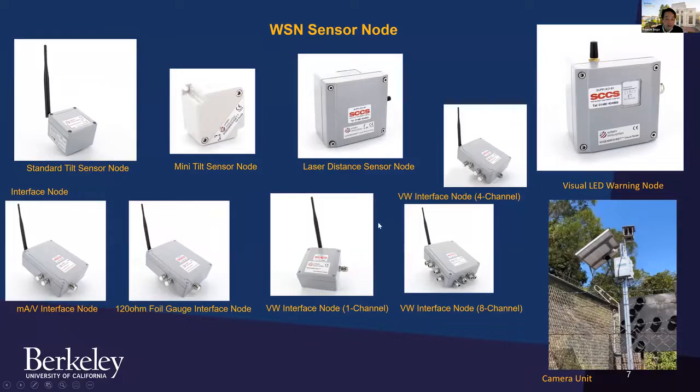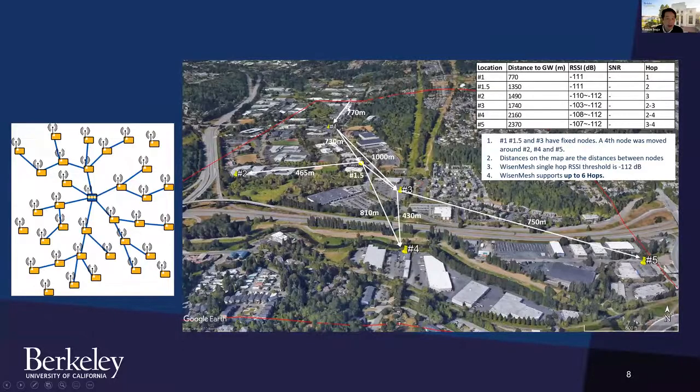One of the big things that happened more recently, in the past 5 years, is the traveling distance. With this wireless sensor mode, you can have one as a gateway, here's another one, here's another one. The data recorded from the fifth can hop to come to your internet network. And now you can see this is going 2 or 3 kilometers, hopping to get the data. These are called mesh networks, and they are common in our field. That allows geotechnical monitoring to be more realistic because you can hop over long distances, for large, long-distance measurements.